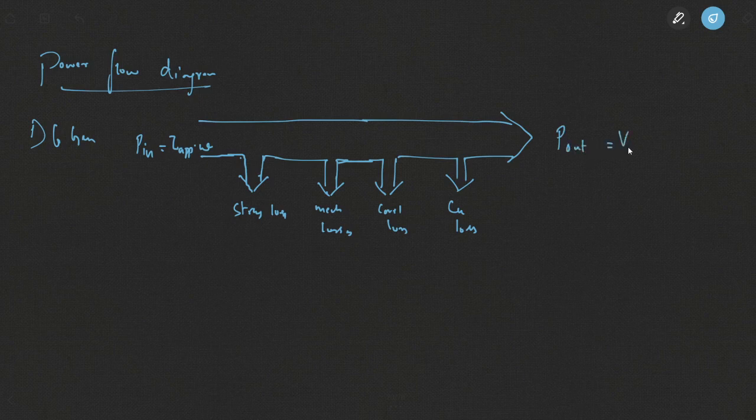You can also calculate the output power in terms of the terminal voltage that's obtained and the load current that's flowing. At this point you will be getting the converted power. That means the power at this stage is converted from mechanical energy into electrical energy, and this is the power that you can calculate through EA, IA, or torque induced into omega m. EA is the induced voltage in the machine, but at the output terminals you will be getting VT.